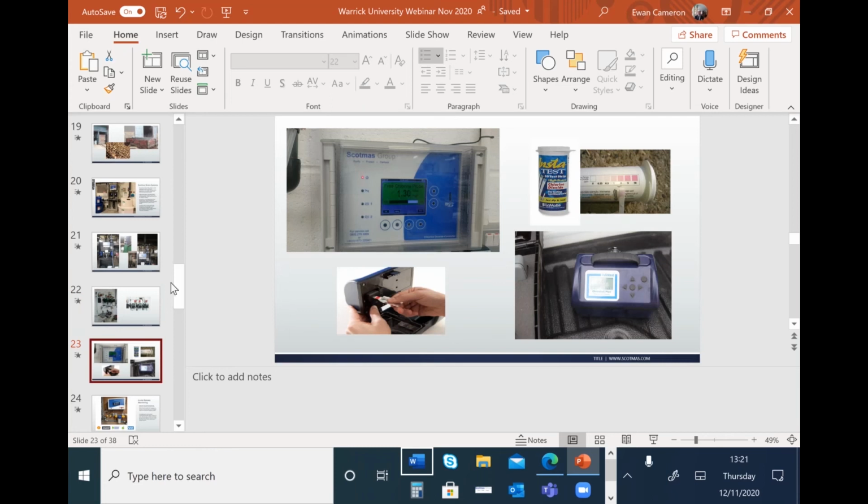So these are just for security and safety. We have alternate methods, as we've highlighted, for measuring the chlorine dioxide. We have simple test strips here, which are very, very cheap. But obviously, this is only of any use if you're manually running your system and you need some control. These other ones here are more sophisticated versions, but they are still a manual check, as is this one here, which is just a wall-mounted pH and chlorine dioxide residual probe.